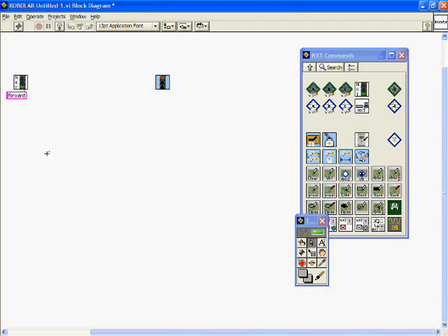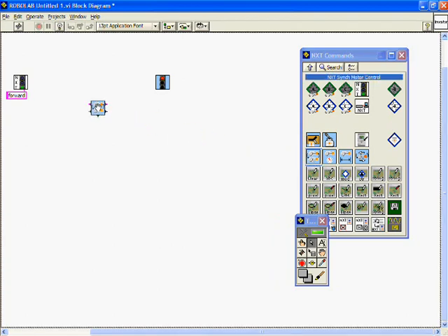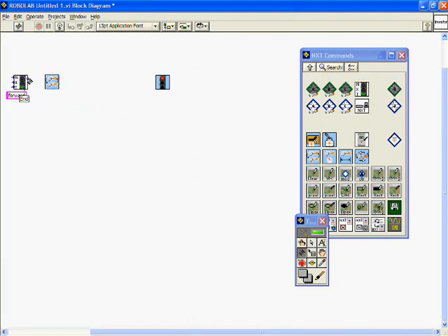The next step is to sync our motors. Syncing our motors means we want both our motors, motor A and motor C, or rather our left and right motor, to be in sync and to go in a straight line. So select the Sync Motor command in your palette, left click and drag. Wire the end of the green light to the begin of this Sync Motor icon, and now notice that there are 5 ports.